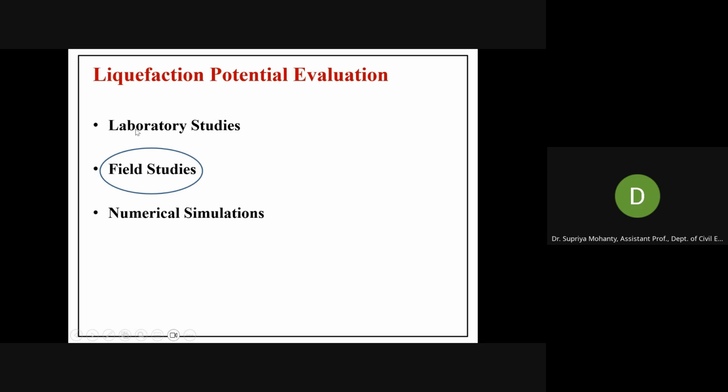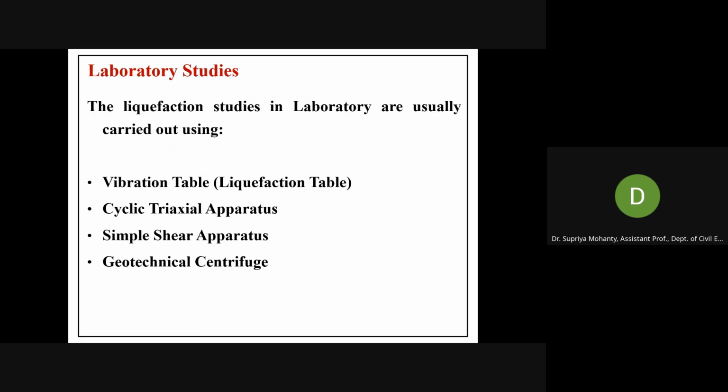However, in the lab study, we can do only a representative sample. We need to collect the sample and try to create a similar environment in the lab, which may not reflect the exact field situation. That's why field study is recommended for liquefaction potential evaluation in our IS code.